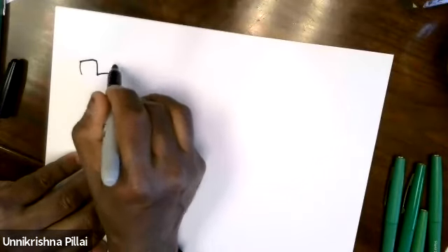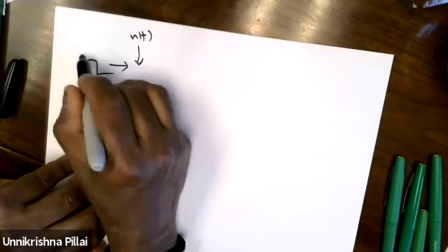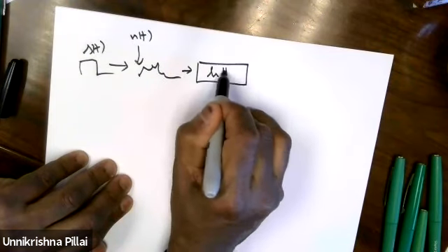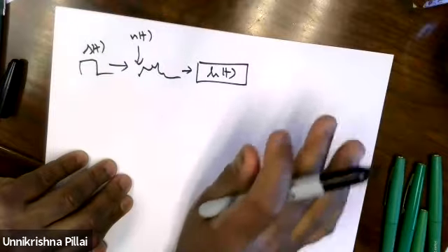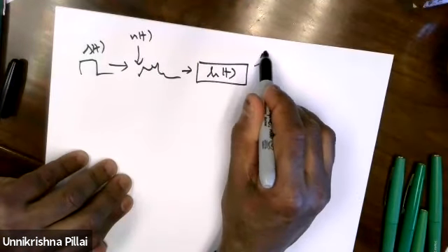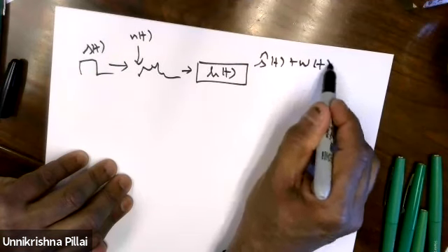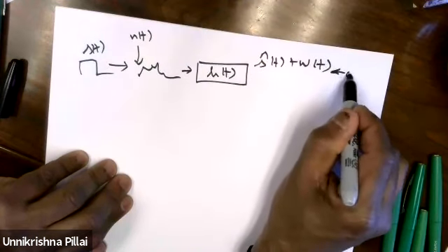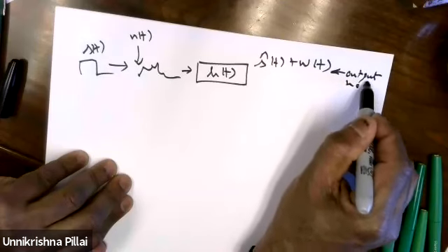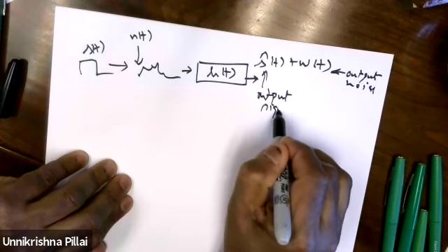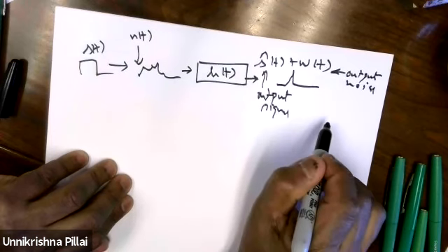The way we pose the problem is, you have a signal coming at you, but in all likelihood there is noise. So what is coming at you is something like this. You want to pass it through a receiver, so that our idea is pulse compression. There will be two components here, the signal component and the noise component. The signal component I am writing as S hat, and W is the output noise. This is the output signal. Of course, you want this to be compressed like this.